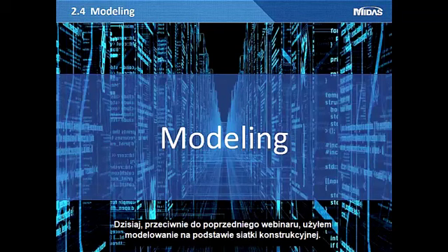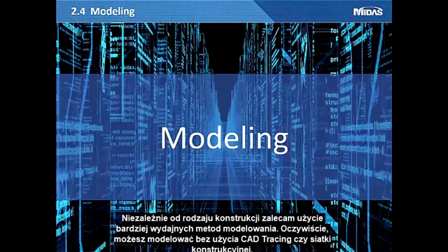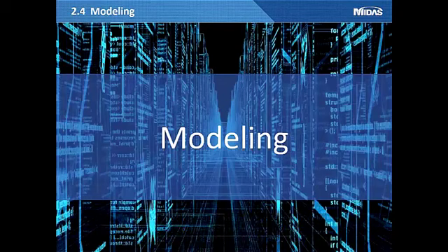Today, unlike the first webinar, I tried to make the model by applying grid information. Regardless of the type of structure, I recommend that users apply the more efficient modeling method. Of course, you can just model without applying the tracing or grid method.